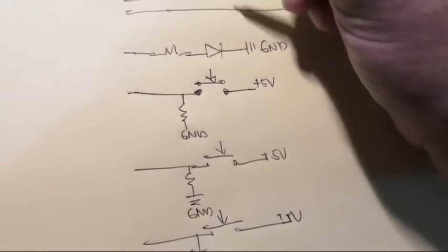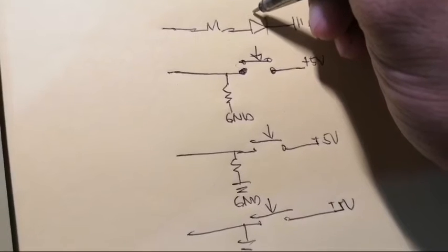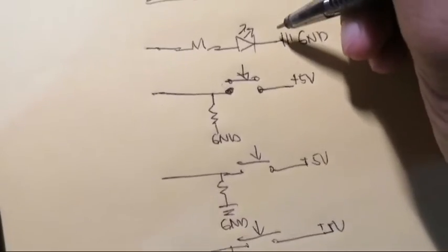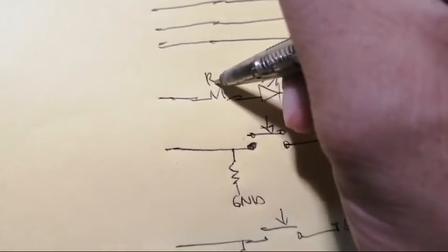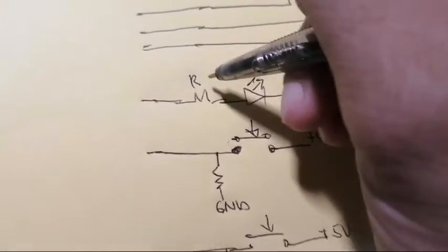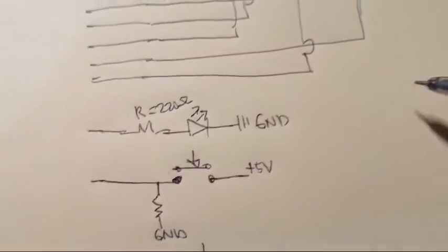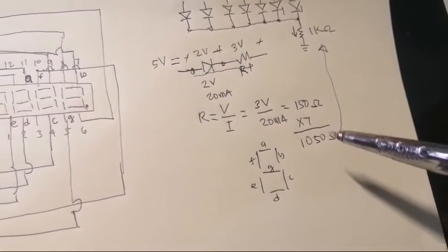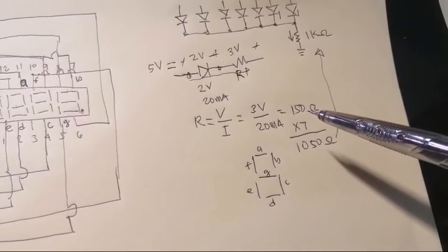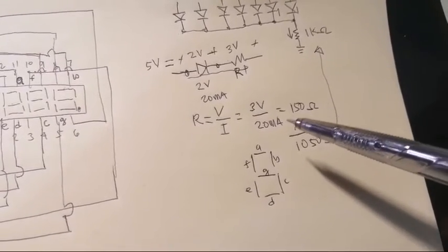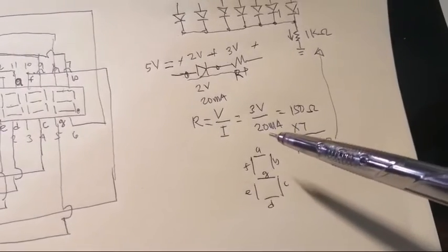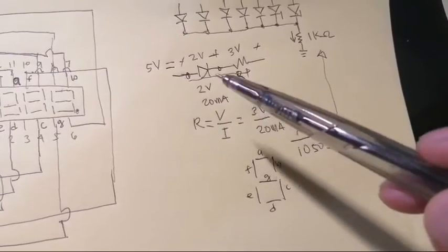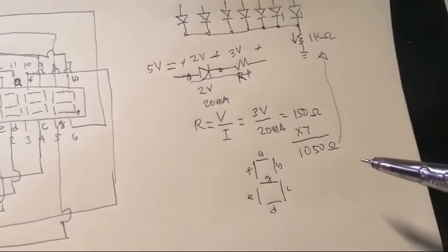So this LED will be used to indicate the second of our digital clock. This resistor we will use 220 ohms. So for computations, just follow this formula. Actually, its good resistor is 150 ohms, but the 220 ohms is also good for limiting resistors. It has an approximately 18 milliamps, which is within the range of the LED.